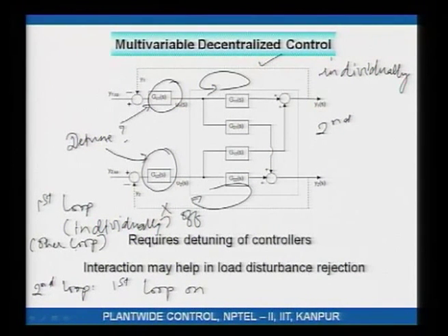If you follow this procedure for tuning, what you will find is that all of the detuning is taken in the second loop. You see what I am saying? So, all of the detuning is taken in the second loop, the first loop is tightly controlled, that would give me acceptable control performance. Okay. What if both the control objectives are relatively equally important? Well, that gets slightly technical, and maybe we will cover this in the next couple of lectures. For that some amount of theory is necessary, and we will do that in the next couple of lectures.